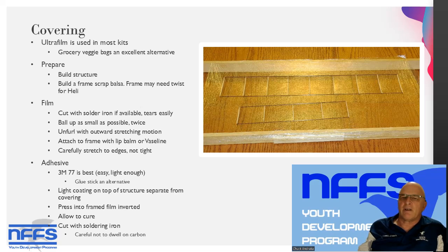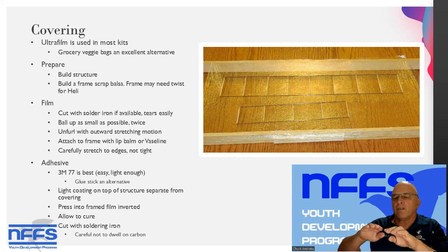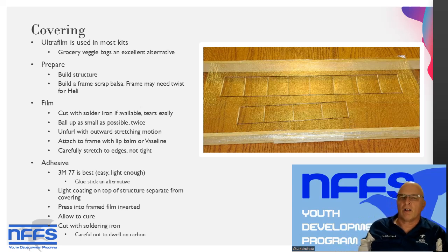And that's going to be especially important on rotor blades, say the X rotor format, where the blade has a twist to it. If you try and put a flat sheet of covering on it, it's not going to go on there well. So you need to ball up your covering and then unball it to get this micro springiness in it.